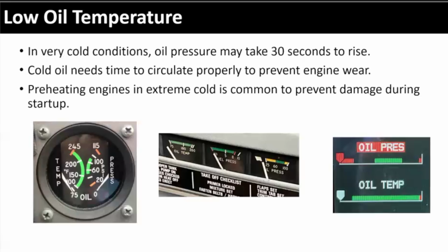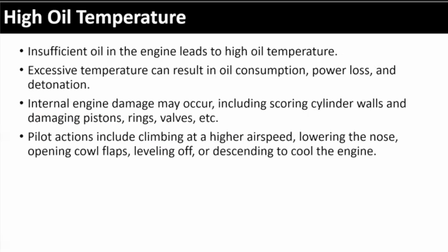We already talked about this. 30 seconds is sufficient. If the pressure is not getting where it needs to be, call it a day and have somebody look at it. One of the things that people will do, sometimes you will see it here, sometimes in other planes, is either keep the plane in a hangar to keep it warm or preheat it. Have a system to preheat the engine, a blower or an engine block heater, to heat it up before you start it. Insufficient oil, we already talked about it, can cause high temperatures and oil consumption loss.